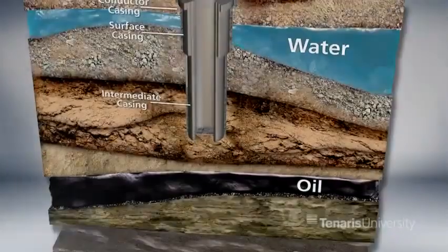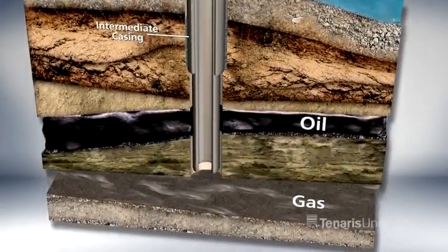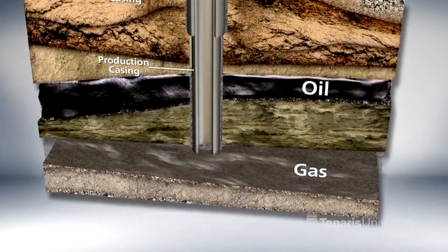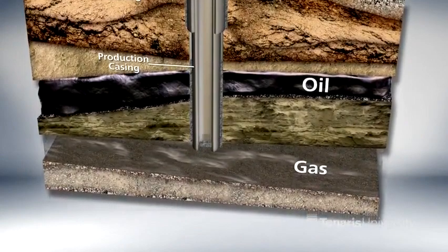Continuing our drilling, we have another string that is the production casing, which is set in front of the productive interval of the well. And now you can see why the intermediate casing previously run is not in contact with the tubing. The production casing is always set facing the tubing. In this way, it must be designed to withstand all the fluid properties such as pressure, temperature, corrosiveness.